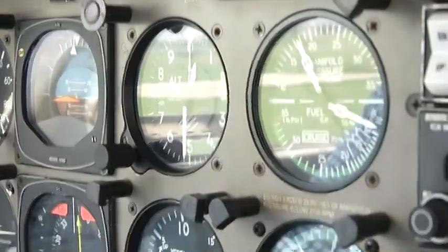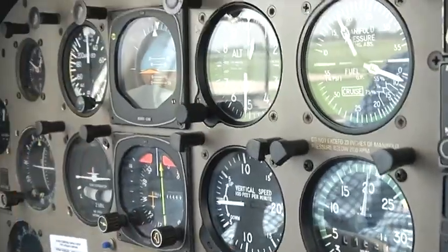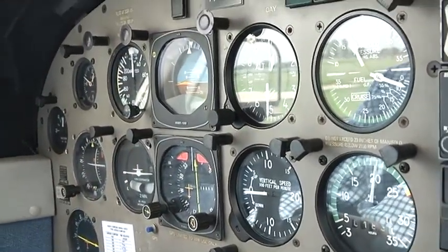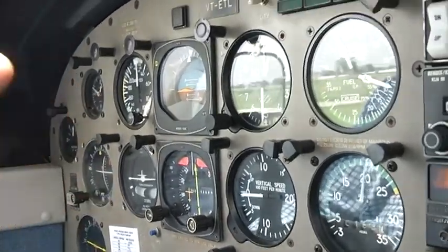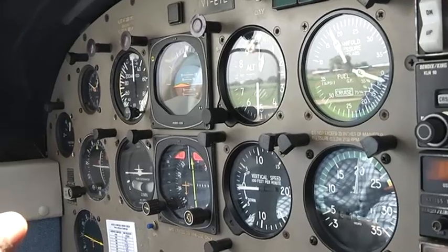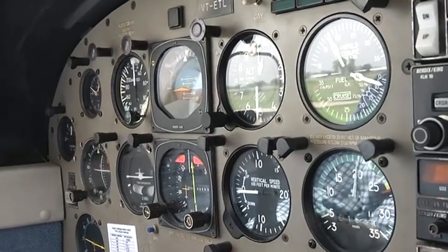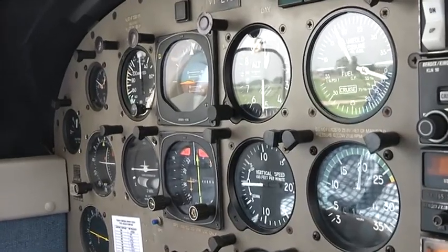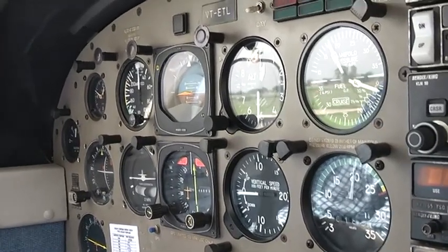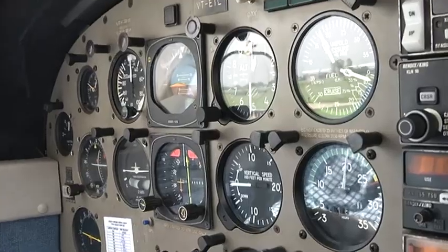Manifold pressure with full RPM should be something around 29 inches of mercury, which, if the engine is able to generate that much of manifold pressure, means your engine is developing power up to its requirements. Whatever the engine is designed for, the engine is generating that much of power.